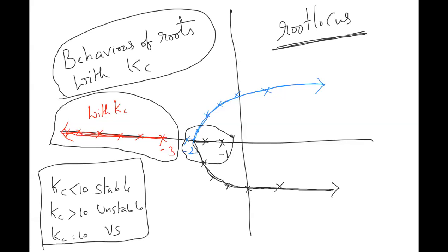That is why, when you are starting new plants, when you start a grassroots refinery, you don't start with a band of, let's say, 0%, because band 0% means you are using the highest value of Kc. That means don't play with the systems when the systems are fast. You have to start when the systems are slow. Because fast systems you can't control, if I directly put Kc equal to 4.5, that means band equal to 0, then the system may go very fast.